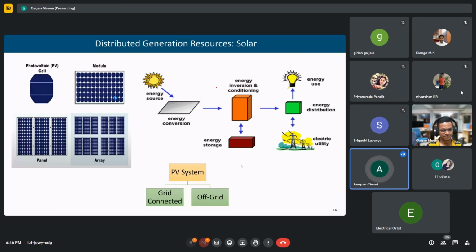A generator has a very huge reactive power producing capability. But I don't think the inverter with the solar cell has such capacity. Yes, that is true, they have a limited capability, but they can provide it, because the solar cell itself cannot provide any reactive power. Only the inverter can. It depends upon its rating, how much reactive power it can supply.